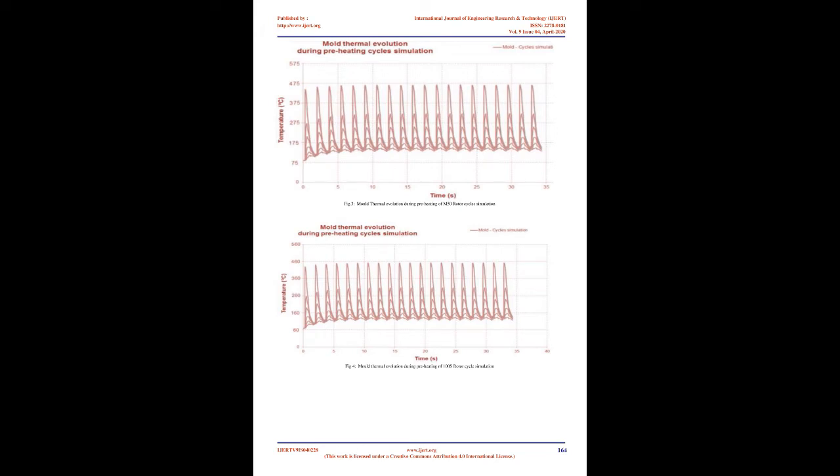Generally, a better fluidity at higher temperature is connected with the decreasing viscosity and surface tension of molten metal with the increasing of pouring temperature, which leads to an increasing filling speed. At the same time, the heat capacity of molten alloy rises with increasing pouring temperature, which increases the filling time. The pouring temperature also affects the microstructure formation to a greater extent, which in turn affects the final structure and toughness of casting products.